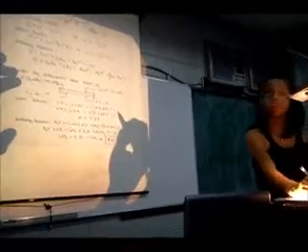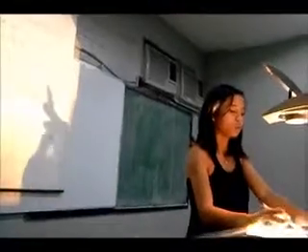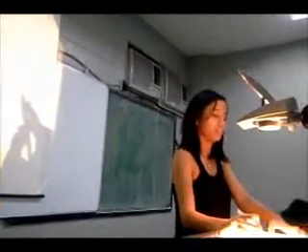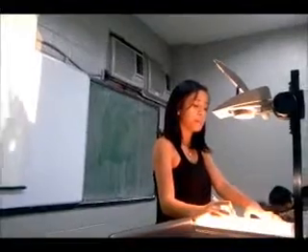So rearranging and cancelling L and V prime Psi, we have dL equals V prime d Psi. And setting up the enthalpy balance, we have HV V prime plus (L plus dL) multiplied by (HL plus dHL) is equal to (HV plus dHV) multiplied by V prime plus L HL.